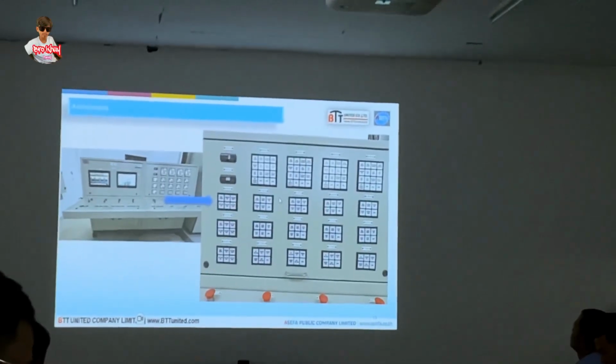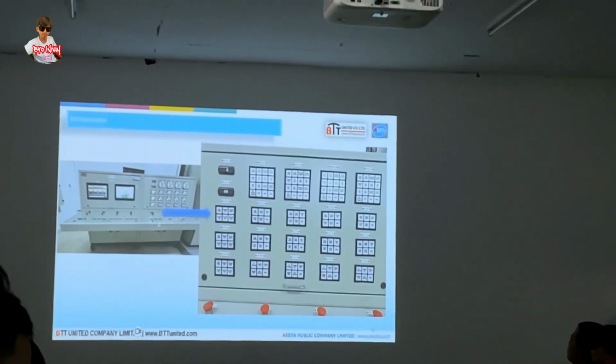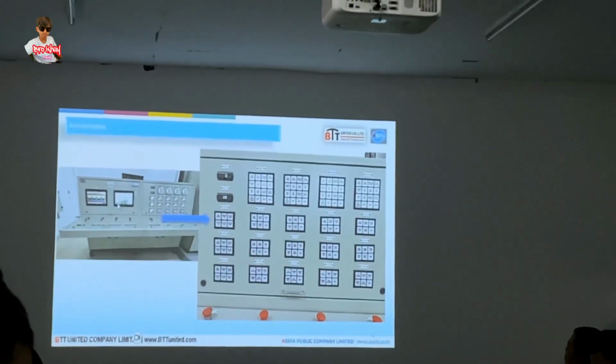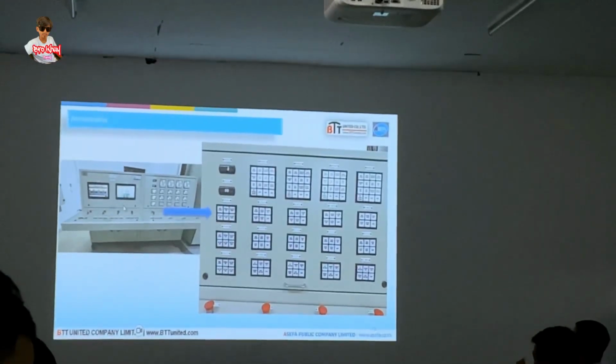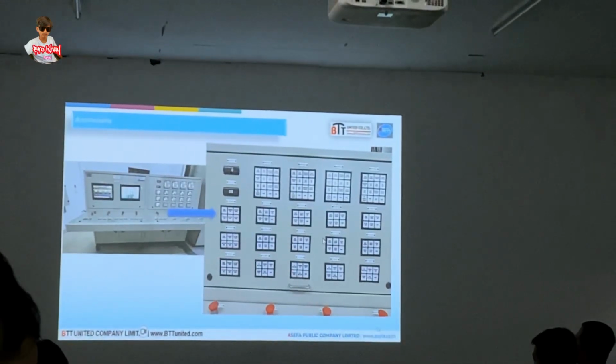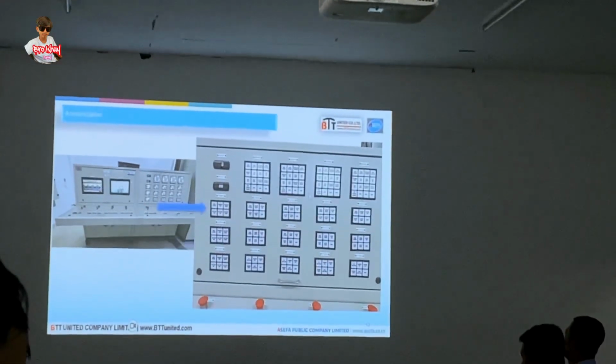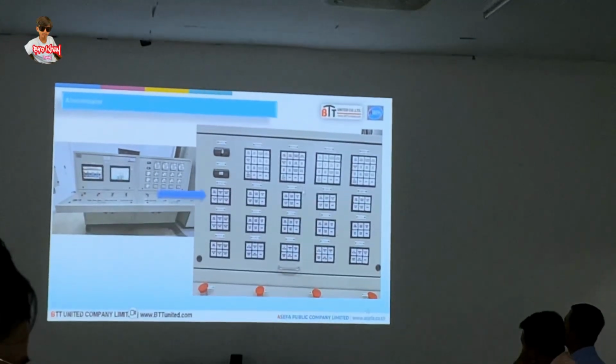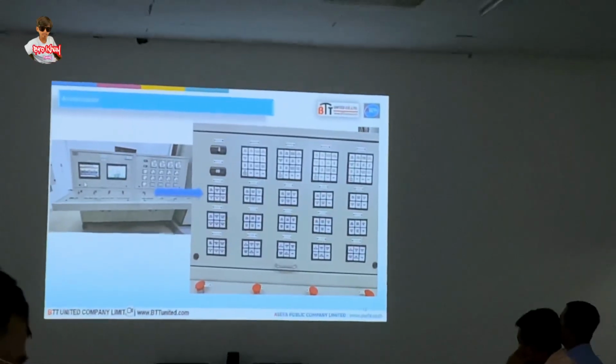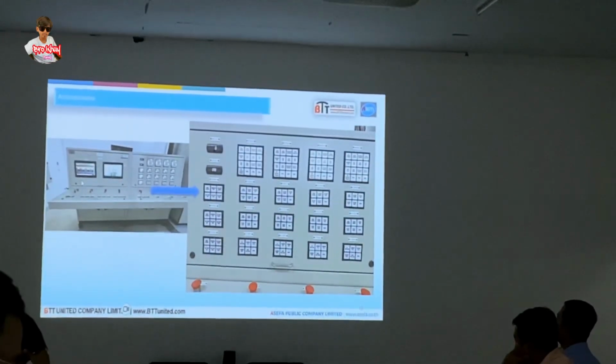Annunciators. Almost exactly the same thing that you have seen on the HMI screen. We duplicate this kind of alarm, just in case the screen doesn't work, so at least you have a backup system. You have your alarms and your lights on for annunciators. In case an annunciator doesn't work, or some lights turn off or don't work properly, you have the HMI display as your backup system.